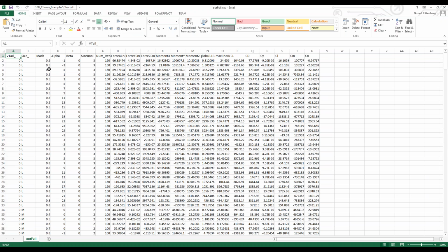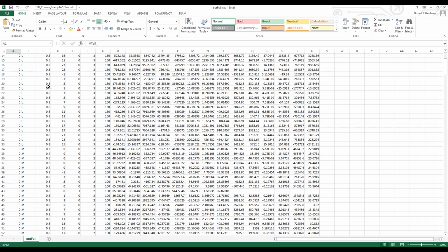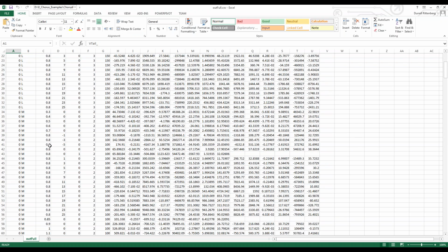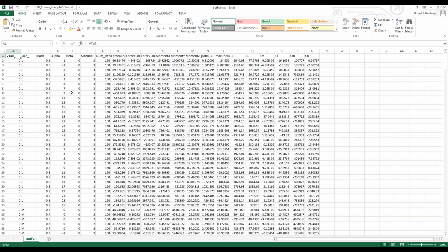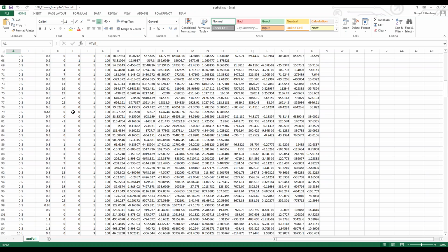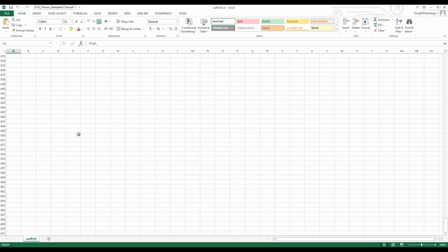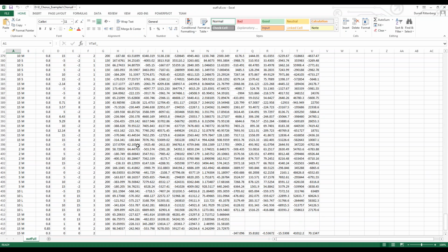We're looking at alpha sweeps from -1 to 25. We're looking at Mach sweeps at 0.5, 0.8, and then we've done a few Mach sweeps in general under a nominal case. We're also doing beta sweeps from 0. If we go up here, you can see that we went as high as 15. So we have lots of information, a highly dimensional space.